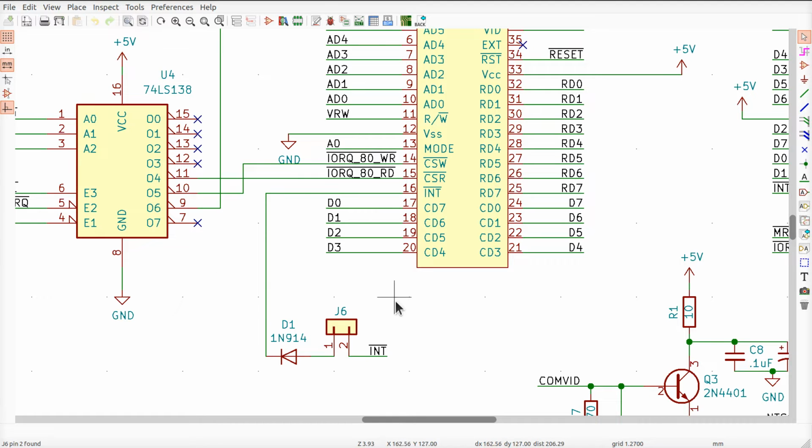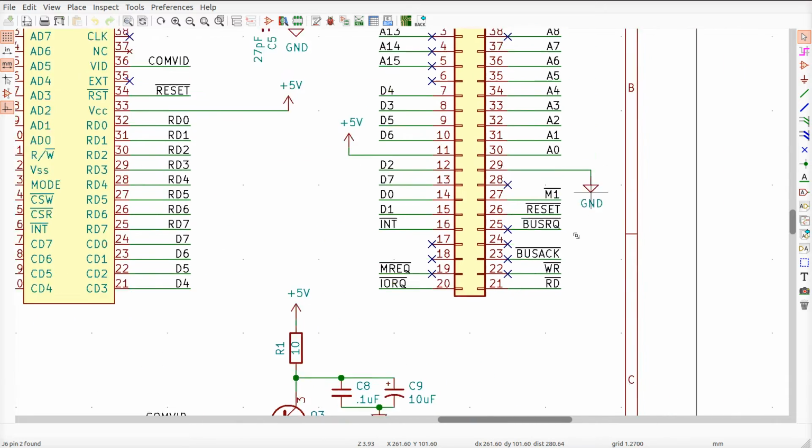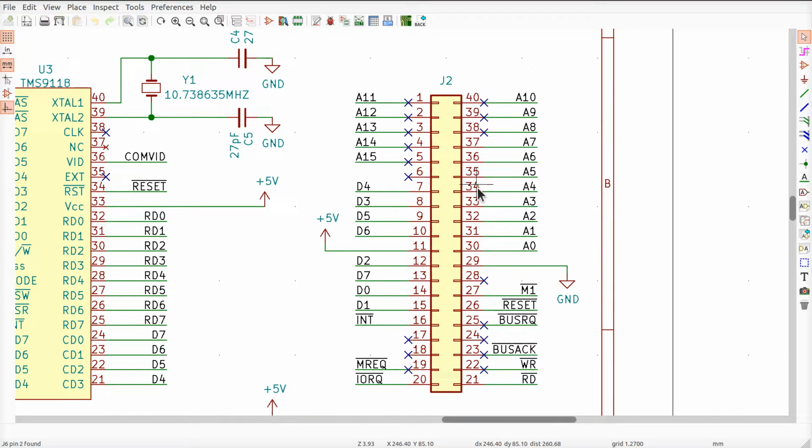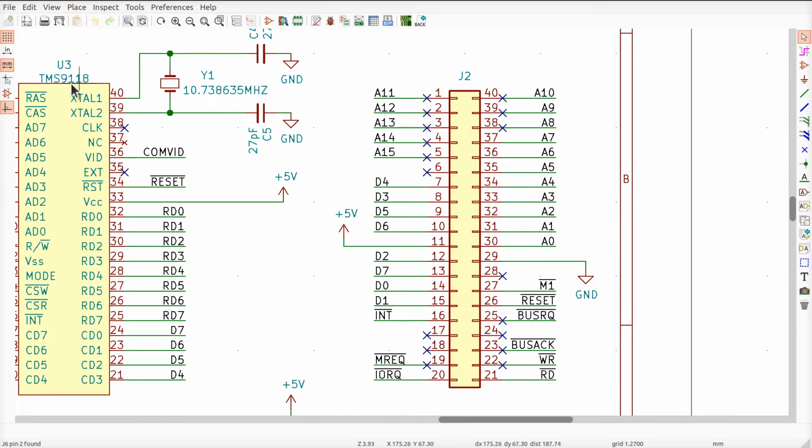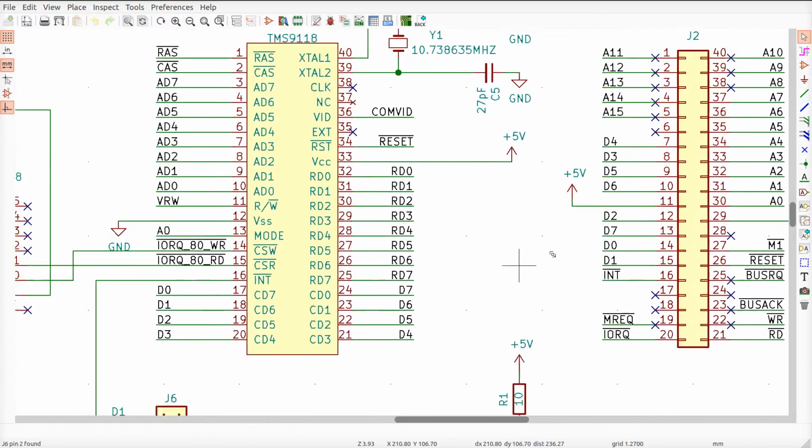Okay. So this is a little bit annoying, and I didn't do us a lot of favors when I did the retro, in that there's no extra pins on the header that comes out over here that allows us to do things like, well, maybe I can send the interrupt output from the video chip over to the CTC or the SIO, for that matter, that could, on behalf of something like the 9118, generate an interrupt in a sane and useful way, and that could coexist with everything else. So sorry about that. Bit of an oversight.